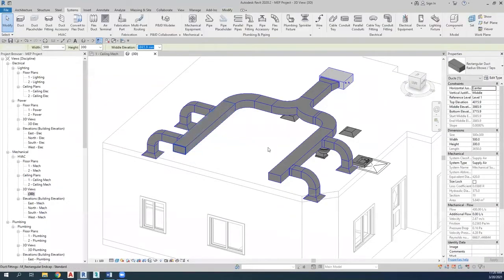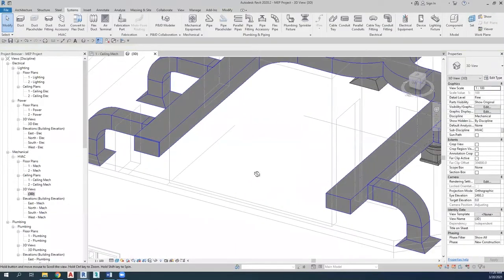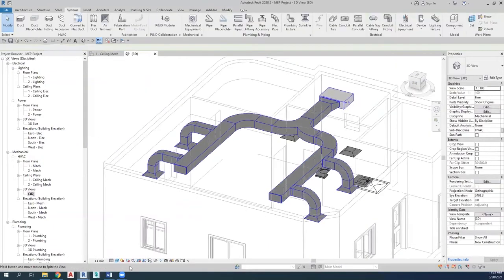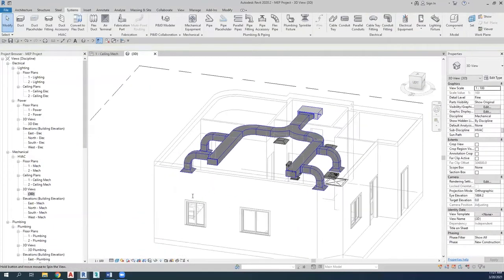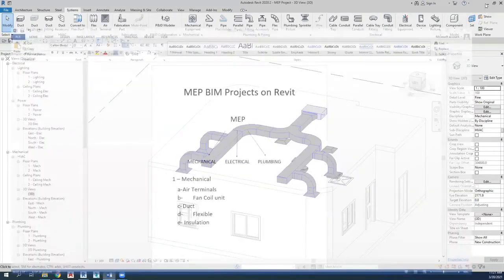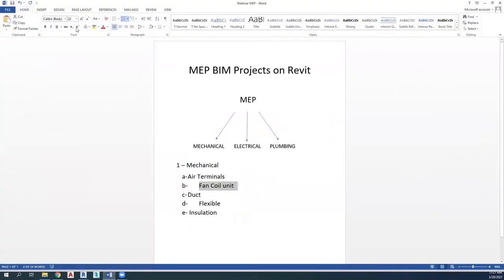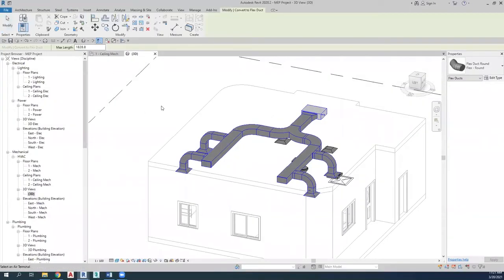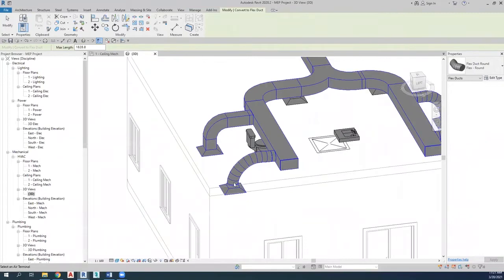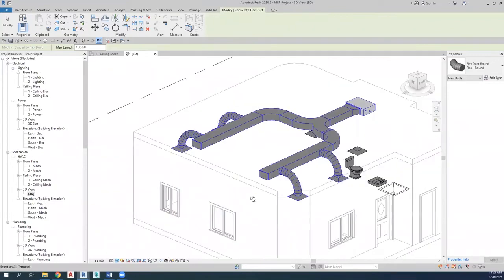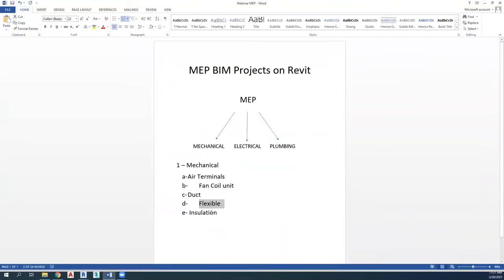Having finished the duct part, we will now be moving on to adding the flexibles. To do that, we have to convert the connections to flexible connections, as seen here. This is an easy task to complete, which results in obtaining more flexible connections. Moving on to the placement of the insulation, having both external and internal insulation.